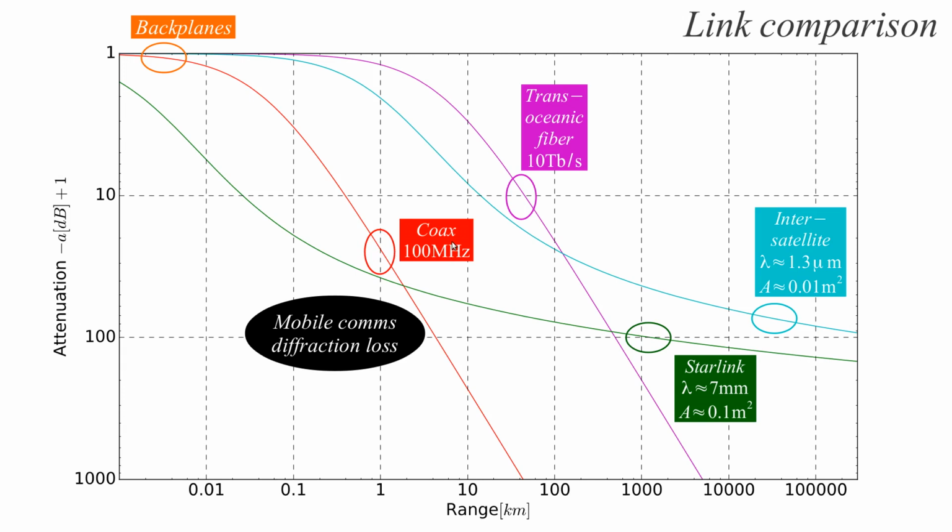Only 100 megahertz bandwidth, that translates into 140 megabits per second over coaxial cable. There were some coaxial cables for 4 times this speed, 560 megabits per second, but they were very rare occasions because of the short range. Fiber has a much wider bandwidth.